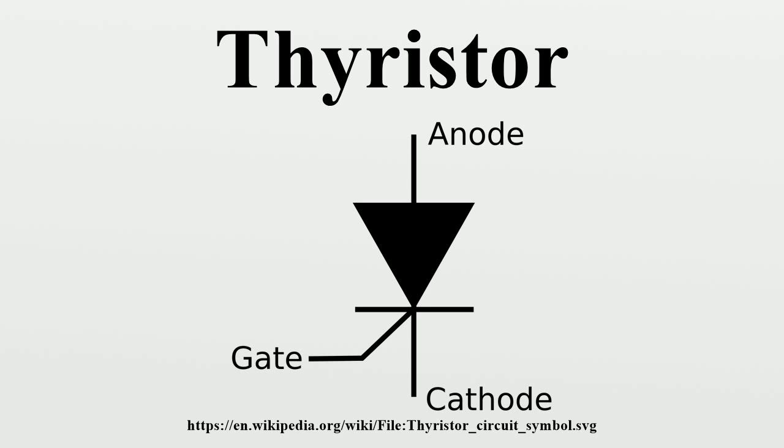Since modern thyristors can switch power on the scale of megawatts, thyristor valves have become the heart of high-voltage direct current conversion, either to or from alternating current. In the realm of this and other very high-power applications, both electrically triggered and light-triggered thyristors are still the primary choice. The valves are arranged in stacks, usually suspended from the ceiling of a transmission building called a valve hall.